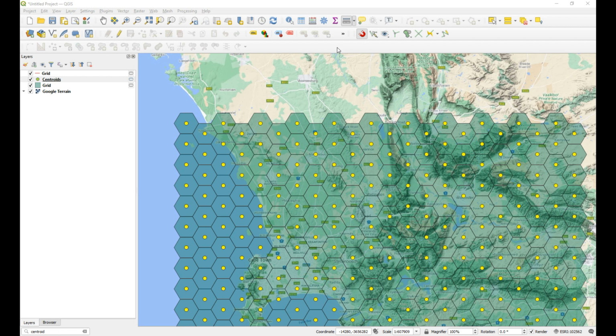So it's a cylinder. What we're doing is we're getting a spherical shape, the Earth, and projecting it onto a flat plane. And in this case, for Transverse Mercator, the flat plane is a piece of paper that is wrapped around the Earth in the form of a cylinder, and then it's popped on its side. That's why it's called Transverse Mercator. And so the point of tangency is the point that that cylinder then touches the Earth.